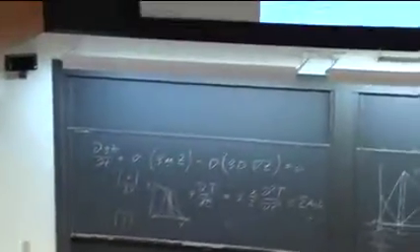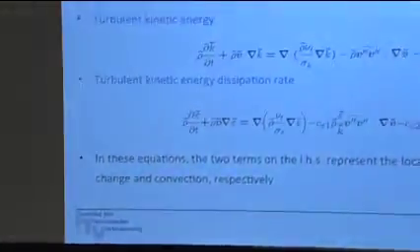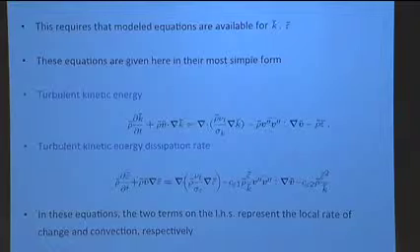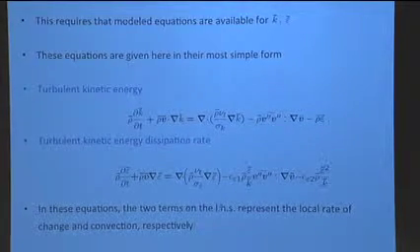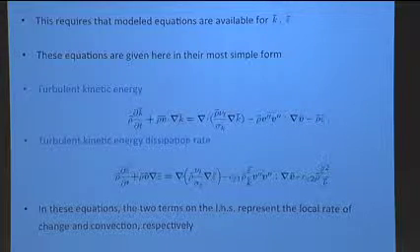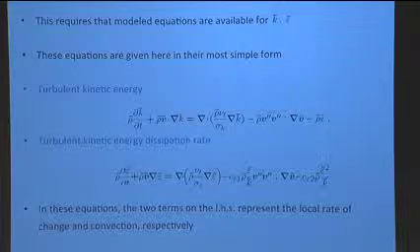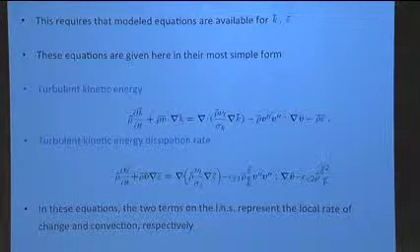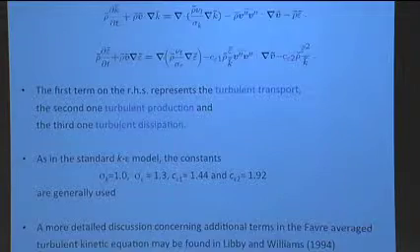And so here, this is a positive quantity, and because it has a minus here, this must be removal of turbulent kinetic energy. Okay, so this is the dissipation, which happens at small scale. So this here is actually velocity gradient squared times the kinematic viscosity. It's very similar in form to the scalar dissipation rate that we introduced earlier. There's also a transport coefficient times gradient squared.